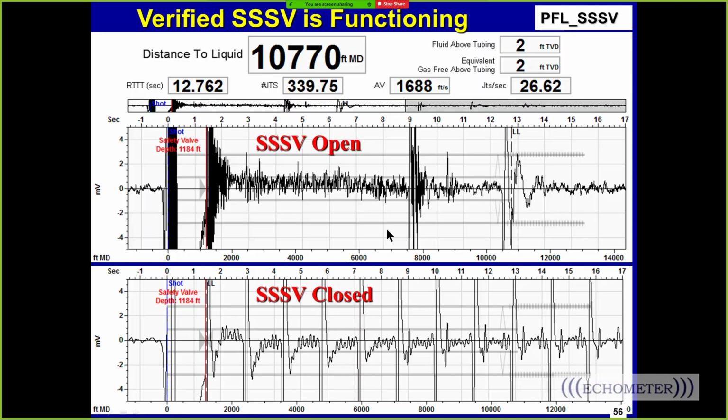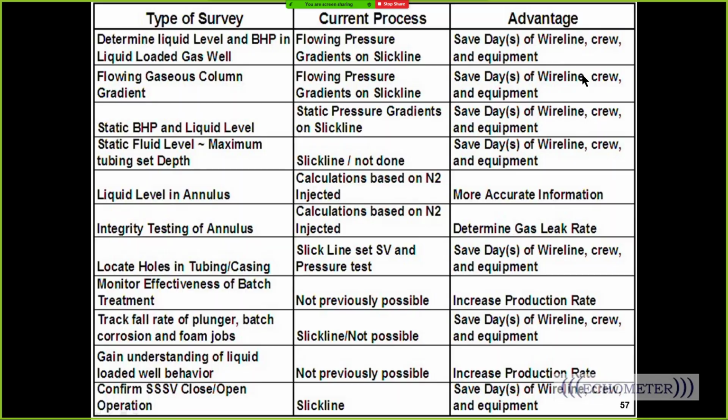This is one last slide here. Here we shot the fluid level on an offshore gas well, and you can see the subsurface safety valve, and you can see this obstruction downhole, like a landing nipple. And you see our liquid level. Well, I think that might be the anchor there, and there's a liquid level. And this is closed, and you can just see the repeat echoes of this subsurface safety valve closed. So here it's closed, here it's open, you can see past it. And that's an example we'll look at in a little bit.